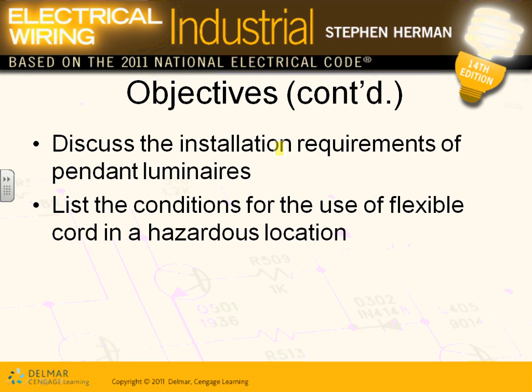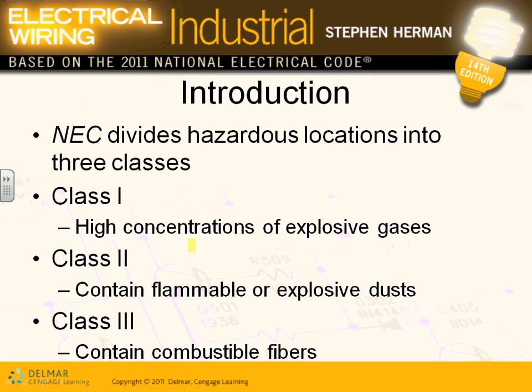A couple of other things, guys. Requirement for pendant luminaires. If you have a pendant luminaire in a hazardous location, we would like to talk about the requirements with rigid, how to mount this pendant luminaire. Flexible: can I use flexible cords in a hazardous location? Yes. What are the requirements for using flex in a hazardous location? You have a machine in a hazardous location. How are you going to tie this machine? Good luck bringing EMT. Well, you can't bring EMT. Bringing rigid directly to this machine, every time this machine moves, it's going to vibrate through the whole building via the conduit system. So, the requirements for flexible in a hazardous location. These are a few things that we're going to do.